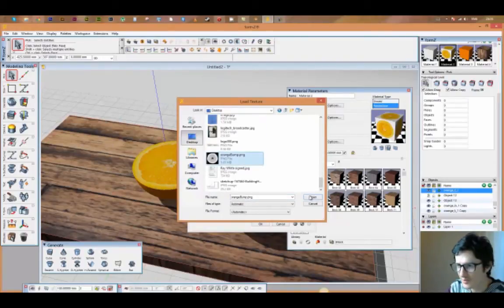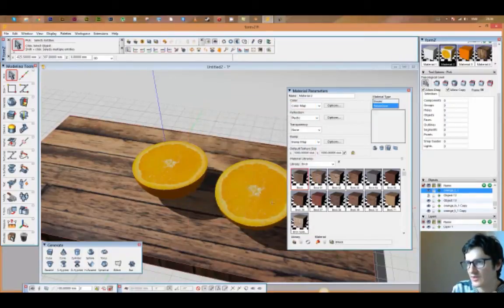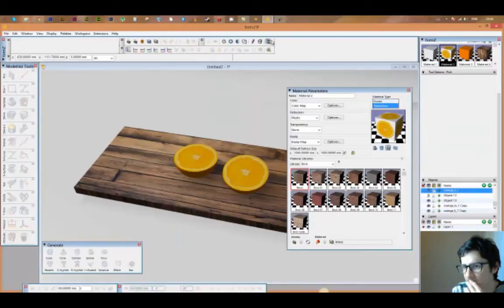That's it there. Okay. Now, you'll need to adjust this smoothness and amplitude to something that makes sense for you. I'm going to go to, say, 16% smoothness and 20 amplitude, and that will increase the depth of the bump map. So for this example, I'll just increase the amplitude up quite high, so it'll exaggerate the effect so you can see it. Okay, and let's give that a render.